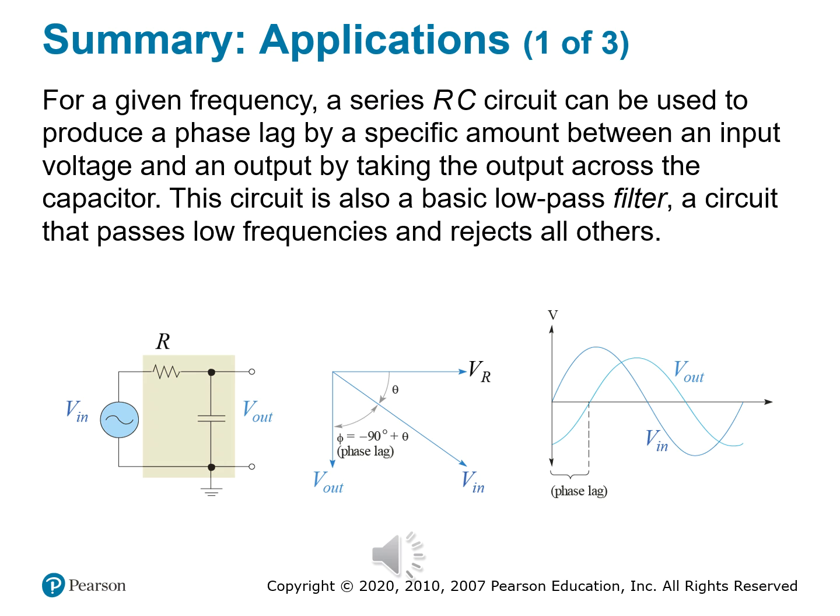So let's go ahead and compare this to the inductive circuits. It's always good to compare now that we have covered two different types of circuits, inductive and capacitive. When we talked about our inductor-based low-pass setup, if you remember, the resistor came after the inductor and the voltage was taken across the resistor. Well, here the layout is reversed, but the goal and the results are the same.